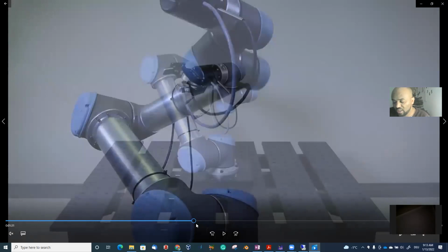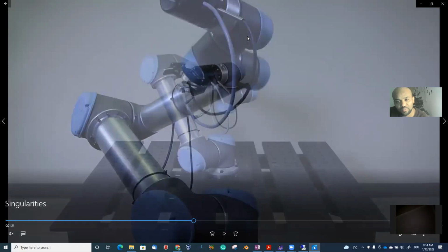So when you model your inverse kinematics for the robot controller, you should take into account that there are possibilities for singularity configuration, and this singularity configuration can be mathematically calculated. By the way, it is not random. You know it mathematically, so you derive it and say if this is happening, then lock the robot system. Then it will lock the joints.